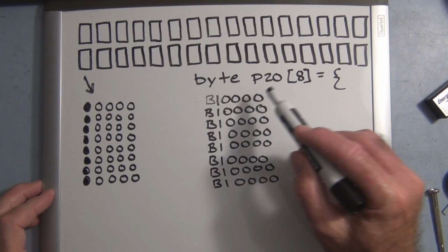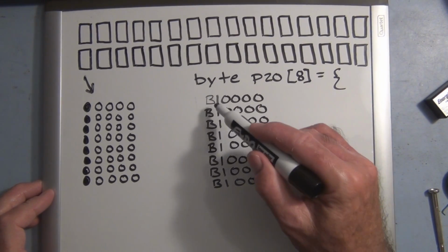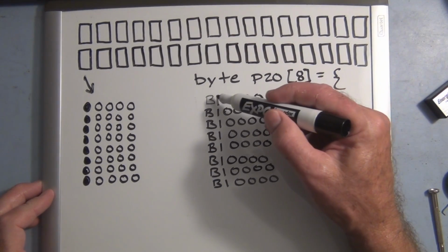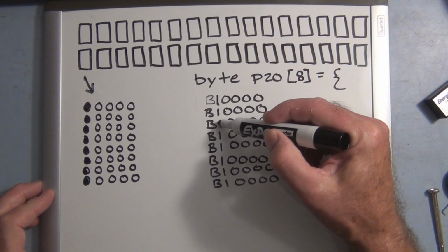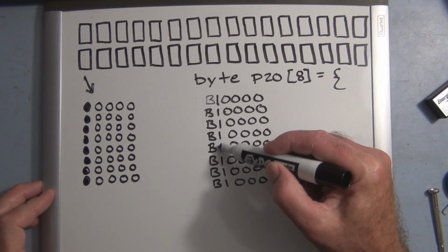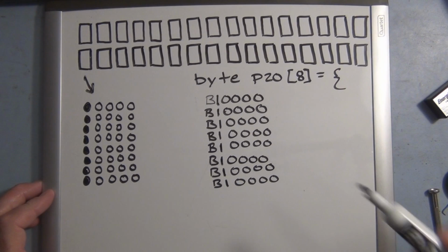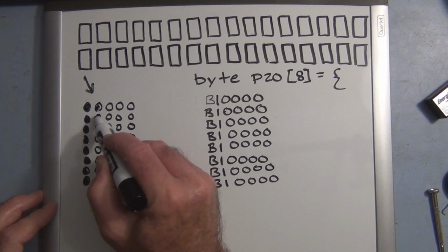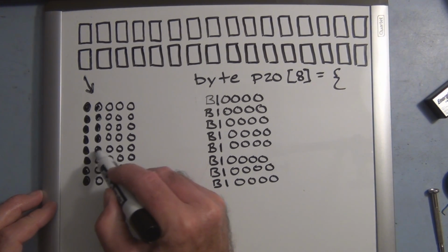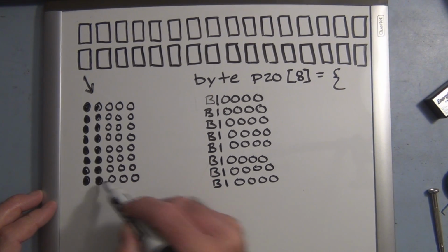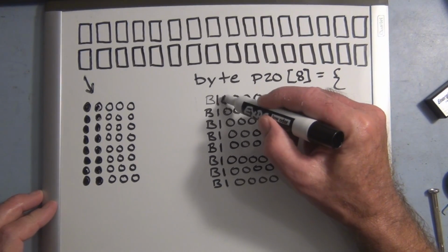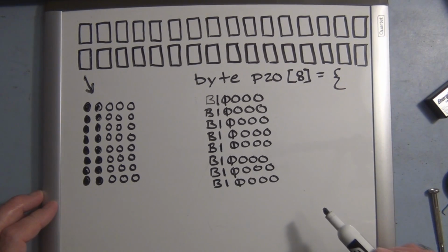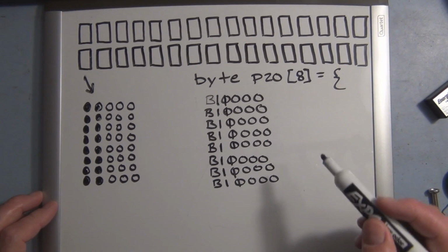We're setting up an array and then telling which one of these we want lit up. And we have B for byte, and then wherever we put a 1, that's going to light up that pixel. So if we wanted the next character, we wanted these lit up, we would change this 0 to a 1, and progress downward as we create.